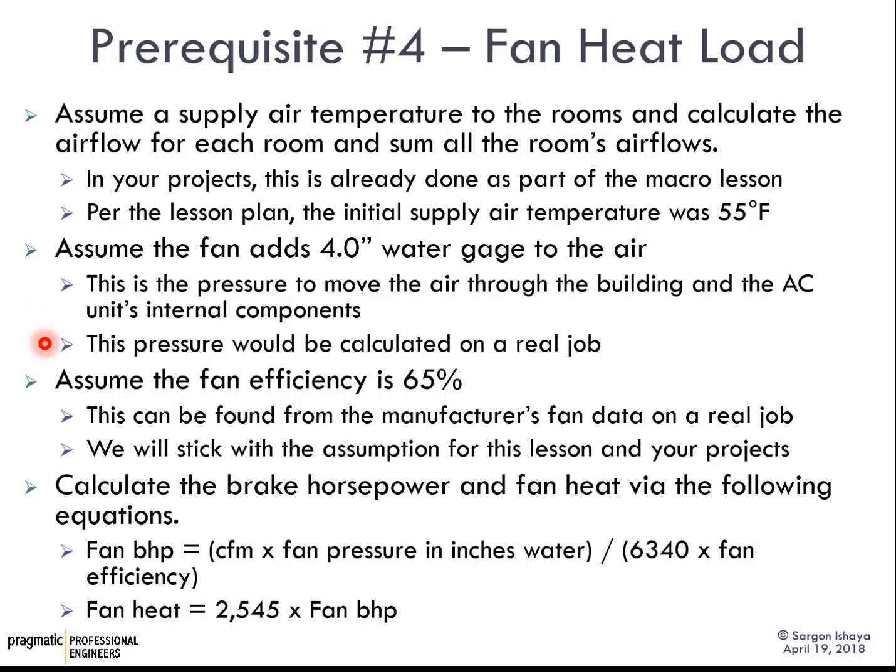In a real job, for example, you would need to calculate this. You would need to do a pressure drop calculation of your duct system. You would need to look at the package unit catalog, which would give you the internal pressure drops across filters and coils and such. And then you would be able to calculate the pressure across the fan.